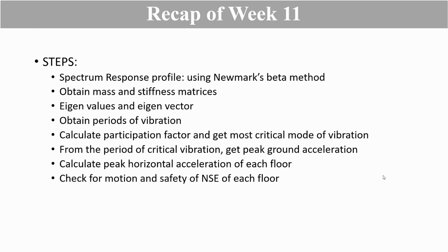Once we obtain the most critical vibration, for this vibration time period, we calculate the earth ground acceleration for each floor, which is generally dependent upon the floor height ratio. So the relationship that we saw in the last live session of mine, like how a particular base ground acceleration is distributed along the height.